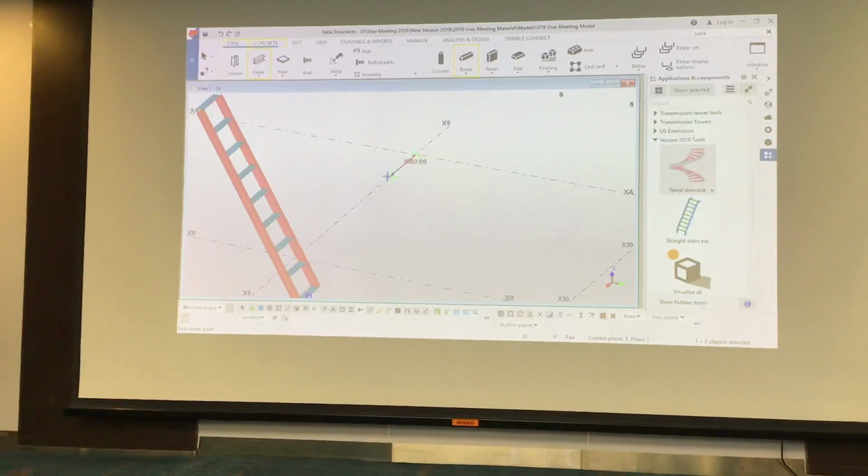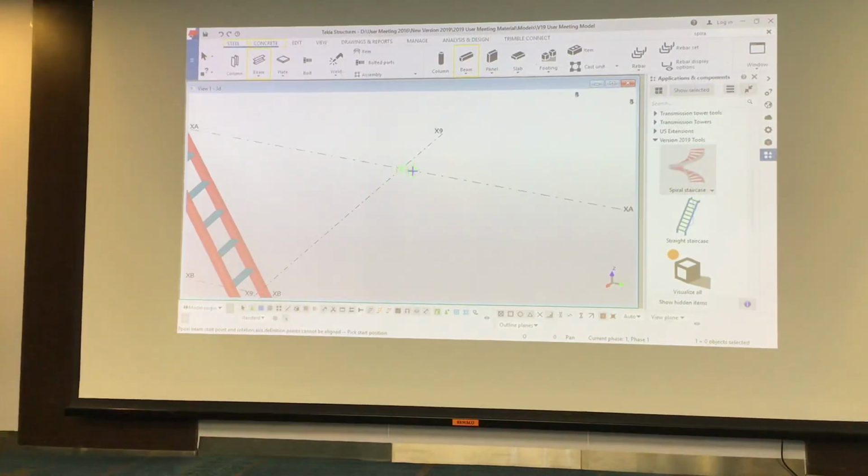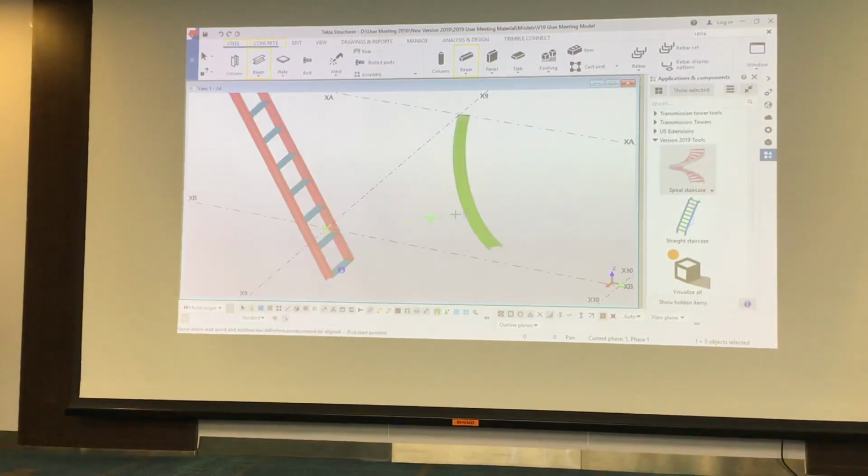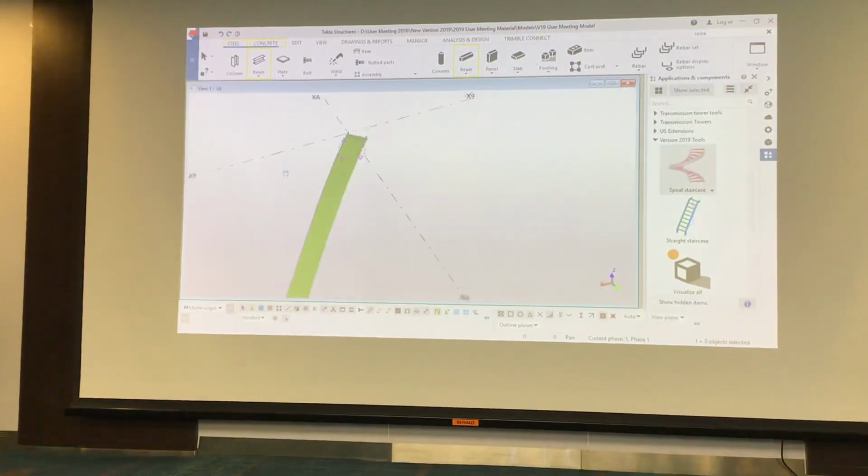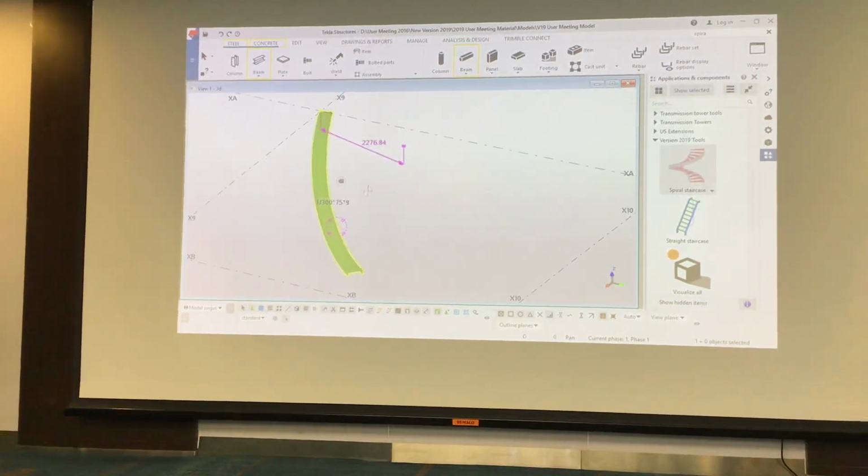I've got to remember how this works now. So let's say from there, rotation axis point is there. Okay, so pick start position, pick center point. Let's say pick that one there, like that. So you can create any kind of rotated curved beam look like this. See it? And if we pick this one up, same kind of thing.